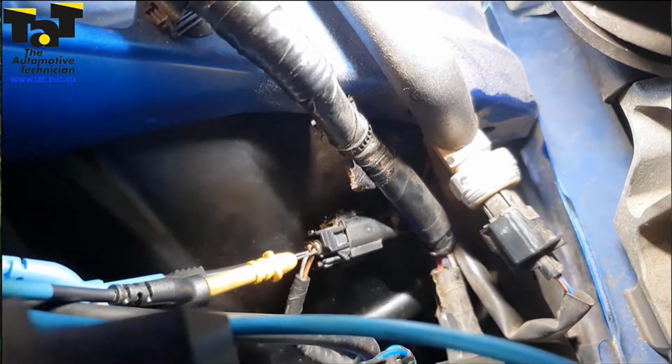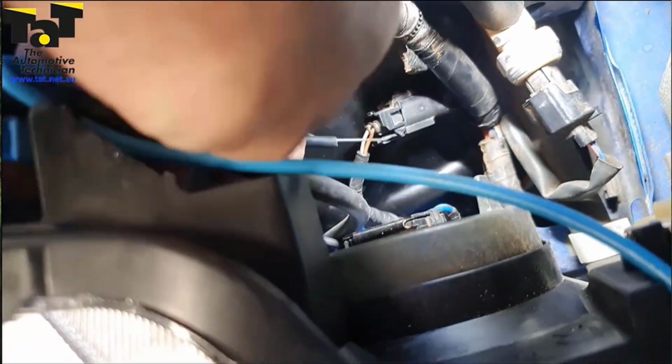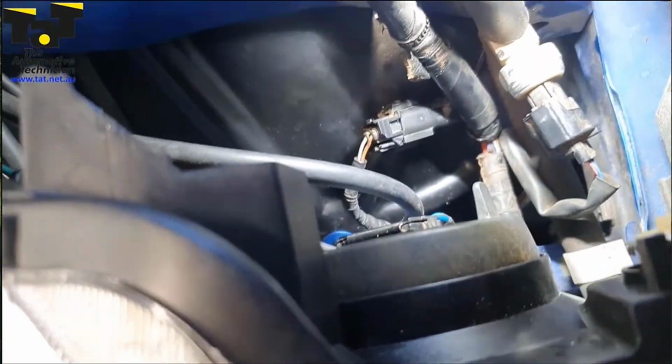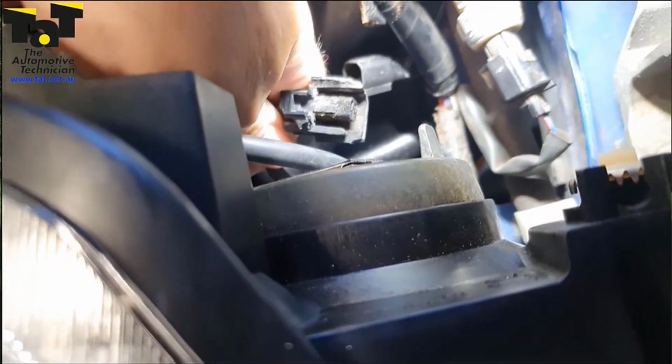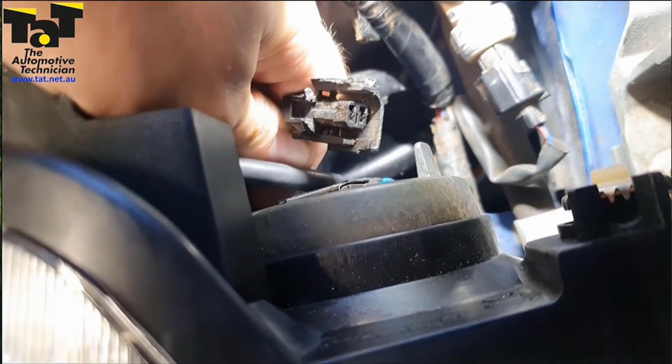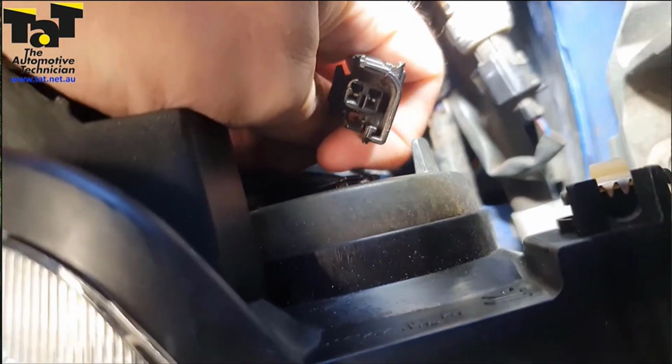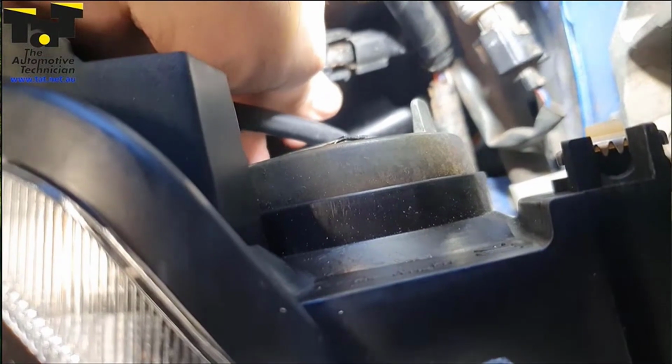But look, I'll just pull this out and quickly show you. There was a massive cable tie holding it on. If you see now, I can basically almost pull that apart. So that's completely broken. We've tightened up those terminals and all is good now, so that is rectified.